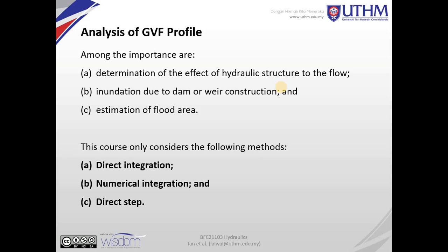Secondly, in the case of dam or weir construction, it may cause inundation of fluid at several kilometers backwards. So therefore, by knowing the analysis using the GVF technique, we can calculate how far the increment of fluid depth along the channel span. And thirdly, we can estimate how big the fluid area is at a certain location as a result of the increment of fluid depth from the GVF fluid type.